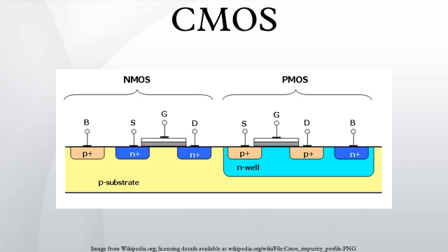On the other hand, when the voltage of input A is high, the PMOS transistor is in an off state, so it would limit the current flowing from the positive supply to the output, while the NMOS transistor is in an ON state, allowing the output from drain to ground. Because the resistance between Q and ground is low, the voltage drop due to a current drawn into Q placing Q above ground is small. This low drop results in the output registering a low voltage.